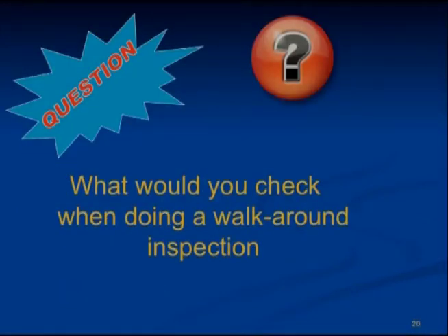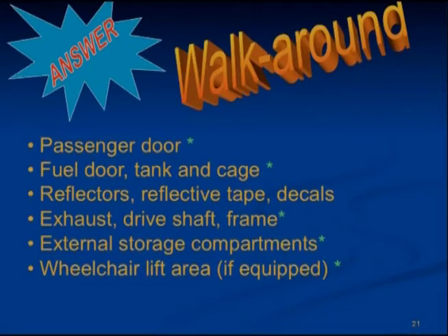What would you check when doing a walk-around inspection? Now, we've covered a lot of material, so let's take the time now to review the walk-around. You begin at the front door side and continue down the right side and underneath the bus, the rear and down the left side of the driver's side, and then back up to the front. Use a flashlight when needed.